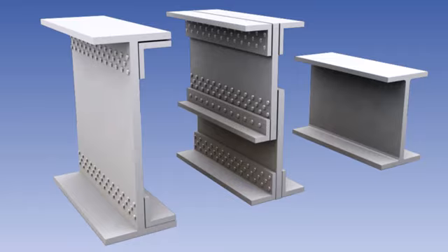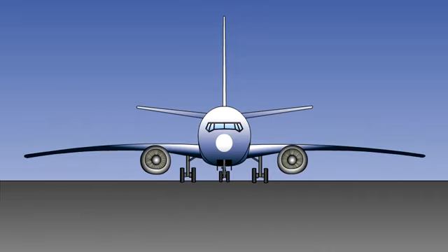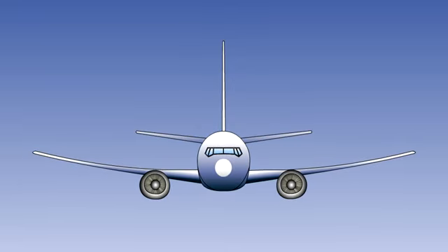The spar will normally be an I-beam either manufactured as a single part or made up of 2 or more parts to give it fail-safe characteristics. These are constructed so that they will absorb the downward bending stresses when on the ground and the upwards, rearwards and twisting stresses when in flight.